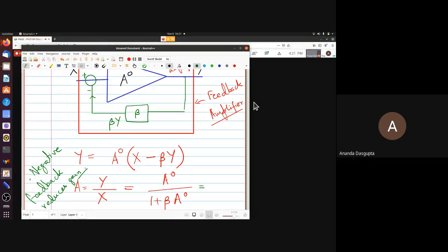I have a feedback factor fraction beta as well. So just to keep things straight, let's talk of the transistor as having an HFE. Now this HFE changes drastically from transistor to transistor within the same batch, changes drastically with temperature, changes drastically with operating point. Again, not necessarily very drastically, but quite a lot.